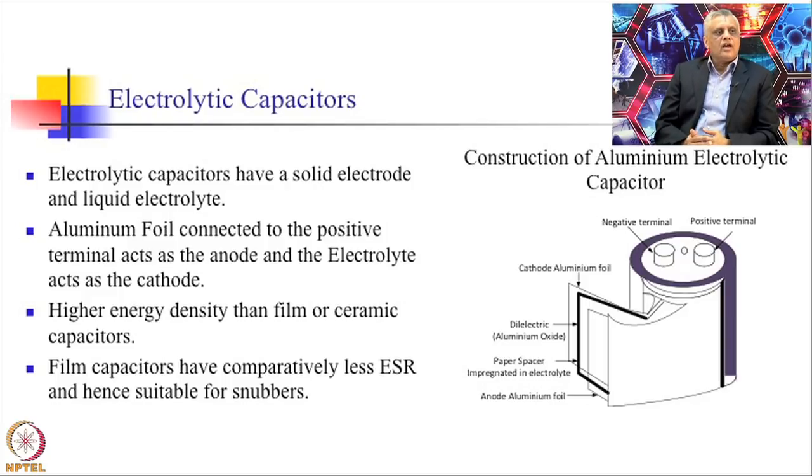Then a thin layer of aluminum oxide, Al2O3, which has a dielectric constant of something like K equal to 8.4, which means that the capacitance we are going to make will be 8.4 times what it would be if air was used here instead of Al2O3. Okay, so that is formed on this etched aluminum foil's body.